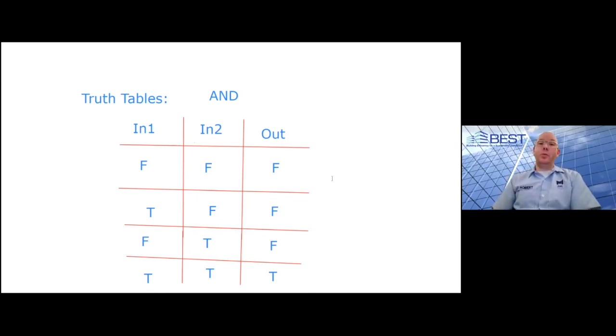number of rows that you end up with. So if you have 5 inputs, that's 2 to the 5th power. And that gets pretty significant because what is that? 32 rows. So you've got to be really careful. Stick with 3 or 4 inputs, 5 if you get really wacky with it. But you can add more blocks down the line to follow through.